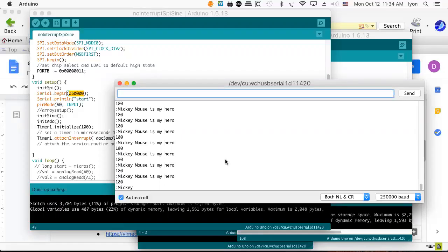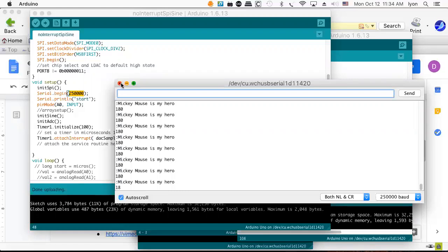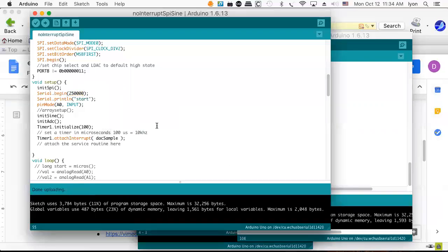And so we've got all these things going on in the background. A to D converters are happening, printing is happening, and it's all because we're interrupt driven. And it looks like it's multitasking, but it's really not. It's carefully dividing its attention between the high priority task, which is the output to the DAC, the lower priority task, which is read from the A to D converter, and the lowest priority task, which is output something to the serial port.